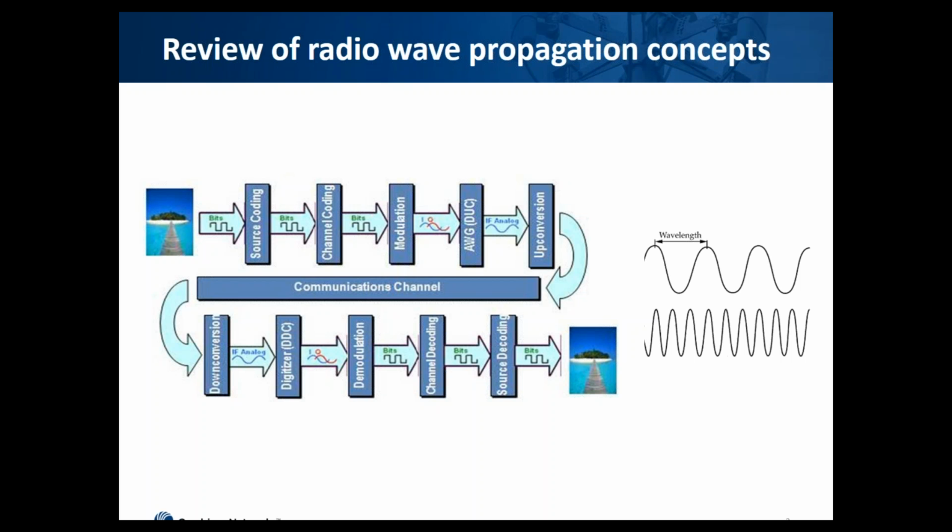Next is the channel coder. The channel coder performs the opposite operation, meaning that it adds redundancy to the data. The reason is that by transmitting additional bits, it's possible to correct some errors at the receiver without having to retransmit the whole signal. How much redundancy can you add? The answer is a trade-off between sending more bits that don't carry additional information and having a signal that is more robust to errors, meaning that the receiver can correct more errors if they occur during transmission.